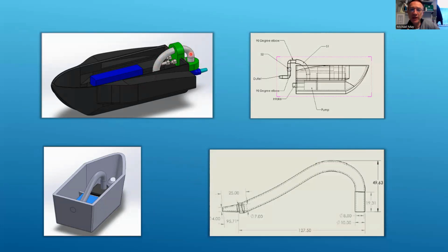The problem is that we, strictly speaking, are working with straight sections and 90-degree bends, and we can work out the major and minor losses for them. But these situations are neither straight sections nor 90-degree bends. They fall in between the two. The closest they come to is what we call a large radius bend, and we don't have a K factor for them. But if you want to experiment by using ANSYS or Fluent to see if you can come up with a K factor for a situation like that, I'm all for experimentation. And just in your presentation, talk about how you conclude the K factor for a design like that.